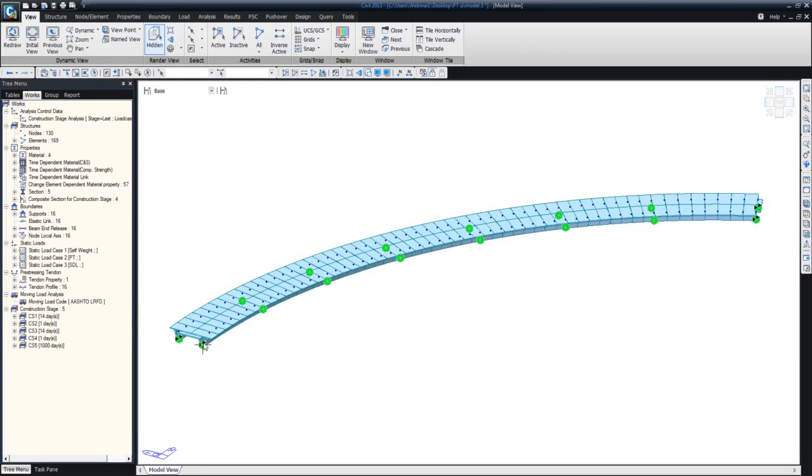So that member is very essential. If dummy elements or the transverse member is not in place, then there is no way that one girder line is sharing load with the other girder line, unless you make this as a fine element model with the webs and deck slab, everything with plate elements.